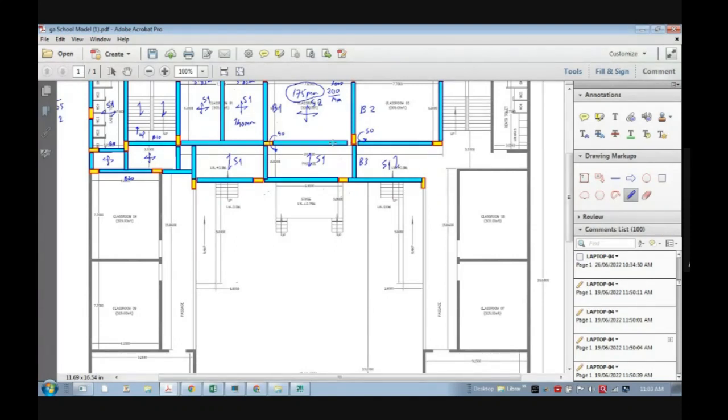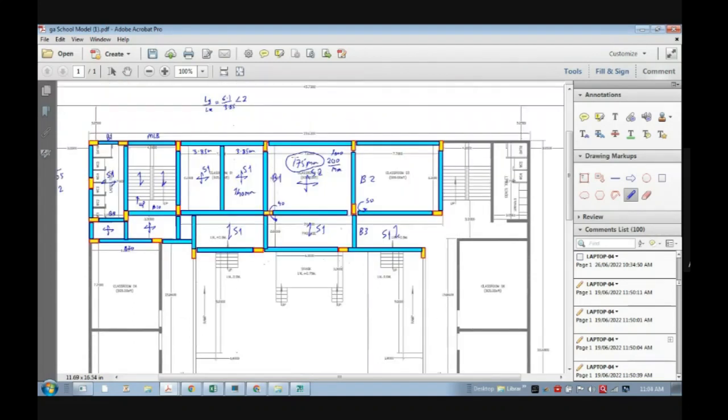Maybe functional or architectural aspects are there many times. Many times floor to floor height is not much as per the planning requirement. And if your spans are bigger, then the thickness of the beam will be very high. So in that case, PT is suggestive. It gives functional benefit, but will increase the cost.